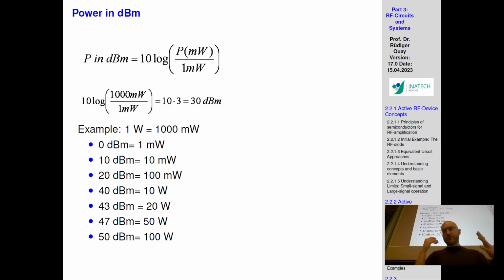So it's easier in the dB scale. Why is it easier? Because it allows you to move from multiplication and division into addition and subtraction. And if you have these two-port devices, these chunks, you're not designing only one two-port device. You're designing multiple two-port devices, and we're going to be talking about decoupling and DC coupling capacitors as well, because you're designing these multiple chains. You don't have only one transistor finger, you have multiple transistor fingers in parallel as well, and besides in parallel, next